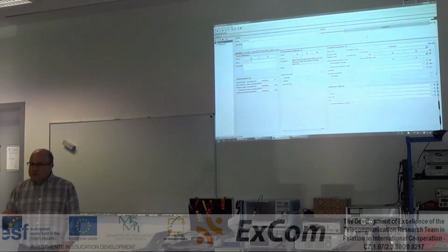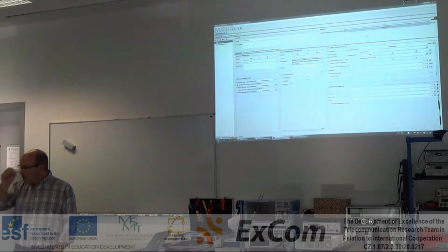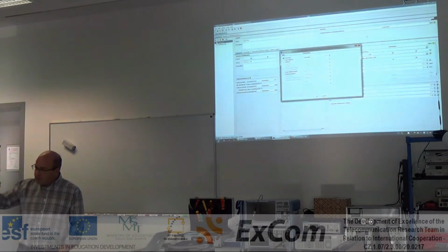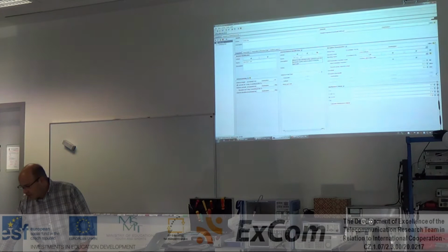For example, if you have a Bluetooth system, you know that the Bluetooth frequency is hopping among 50 or more channels a lot of times. So you can define these specific channels. Instead of using one frequency, you can define a lot of frequencies. For that, you need to define a stair cumulative probability. I will tell you how to do that.